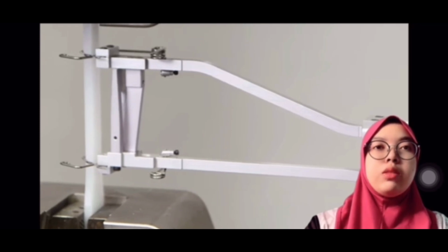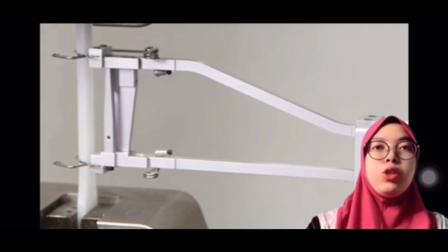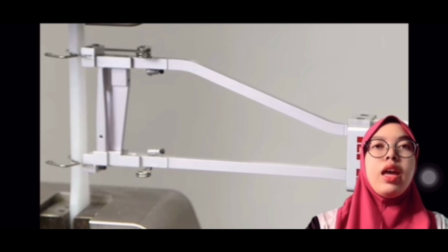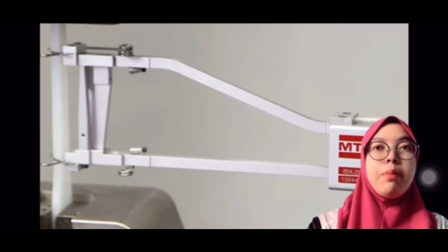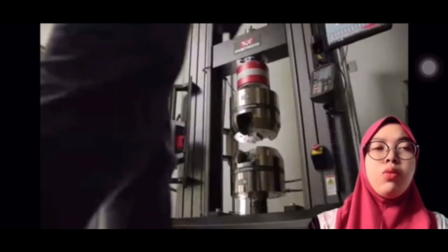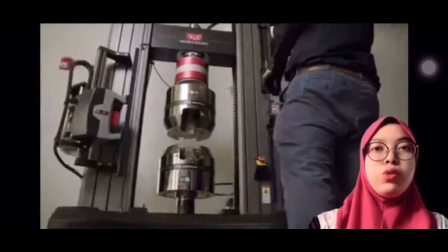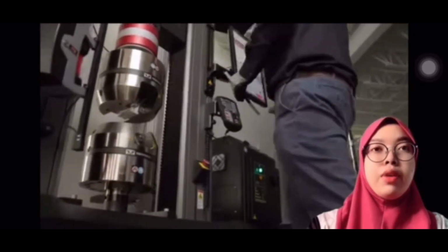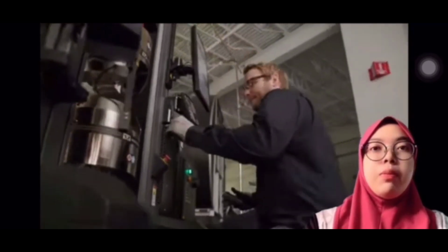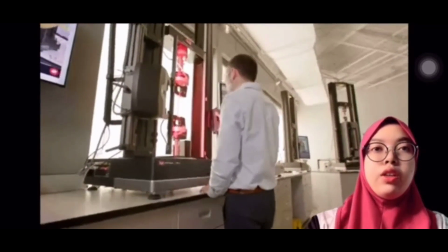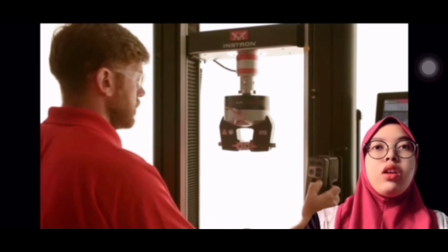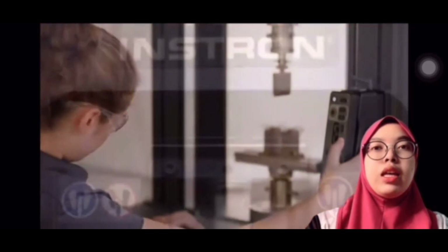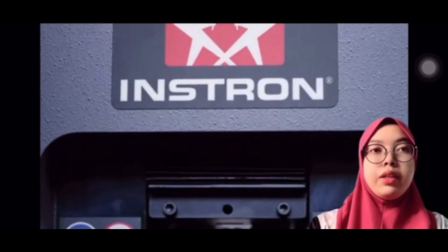After the specimen is placed in the grip, an extensometer will be attached. An extensometer is a device that is used to measure the elongation of the sample. Now you may be thinking, why can't the load frame be used to measure the elongation? Well, you are right, the crosshead can measure elongation, but it will not be as accurate. There are too many other pieces of equipment between the crosshead and the bottom of the load frame to provide a reliable result for the elongation of only the specimen.